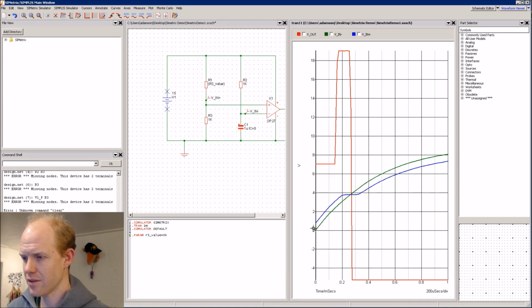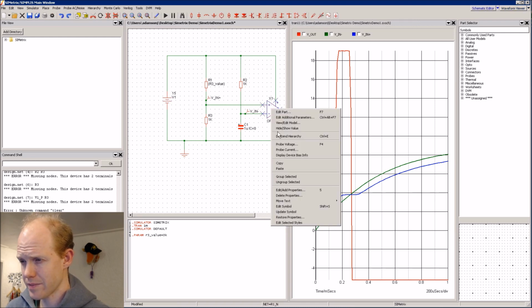And we see here the positive blue, negative green. So we have the positive above the negative at the beginning, so the op amp should be high. And then when they cross over, the op amp goes low. And you'll notice that these guys are kind of tracking each other here, which is a little bit odd looking at first, but that's because this model here has back-to-back diodes.